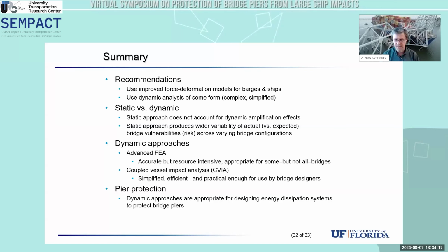So dynamic approaches that are available to us, again, LS-DYNA, very high resolution analyses are certainly very useful and would be appropriate for some cases, but not all cases of bridge design. A more simplified, efficient procedure like the coupled vessel impact analysis procedures or methods of that type are simple enough and efficient enough to be used in practical design by bridge designers.